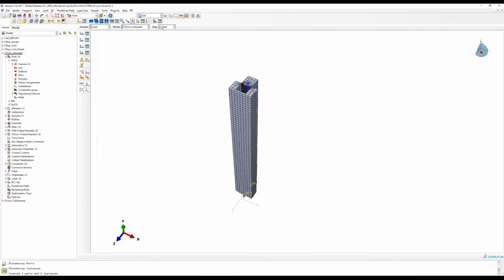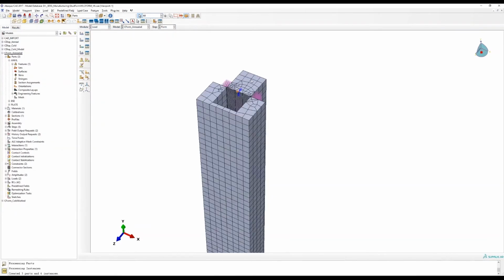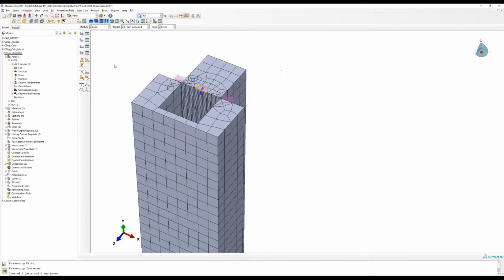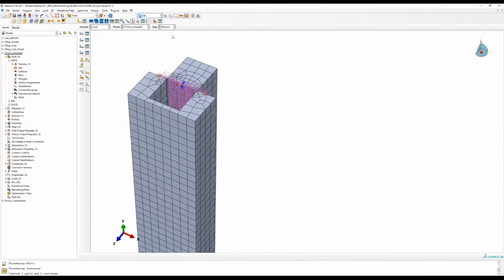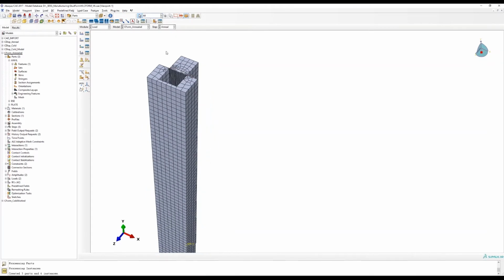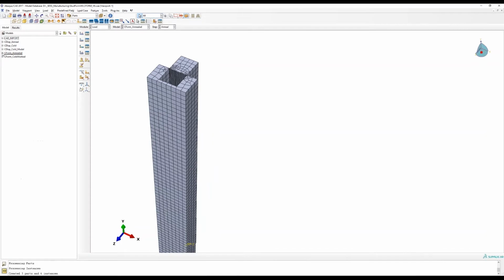Basically, what we're going to do is we're going to move the backing plate in for that first forming step, and then we're going to pull away the fixture in a second step. The anneal step, all that does is set the temperature to reset the stress state, and last we have a settling step where we're going to import it to the bend test analysis.